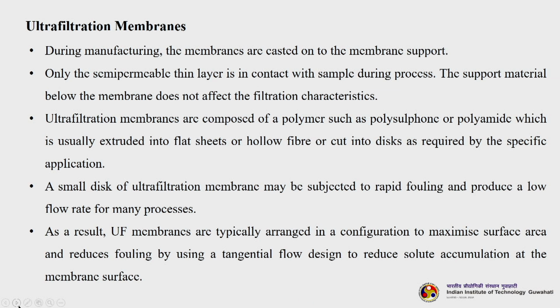During manufacturing of the ultrafiltration membranes, the membranes are cast onto the membrane support. So, only the semi-permeable thin layer is in contact with the sample during the process, right. So, the support material below the membrane does not affect any filtration characteristics. Ultrafiltration membranes are composed of a polymer such as polysulfone or polyamide, which is usually extruded into flat sheets or hollow fiber or cut into discs as required by the specific applications.